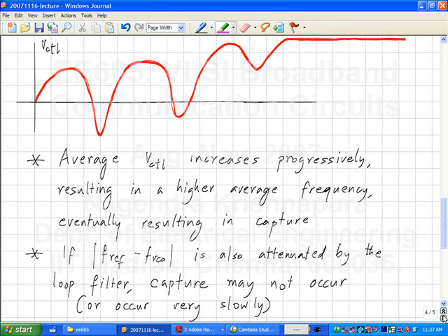So it does tend to do that. So it can in fact do something like this. Okay, it will do this, but then these things will become progressively thinner, and also their levels will get elevated because of the larger DC value. So the next cycle the error is less, and then it may do something of this sort. The control voltage is at the difference frequency. In case of a multiplier, it will be a sinusoid. Okay. Yeah, it goes and it can come down and go back up and so on.